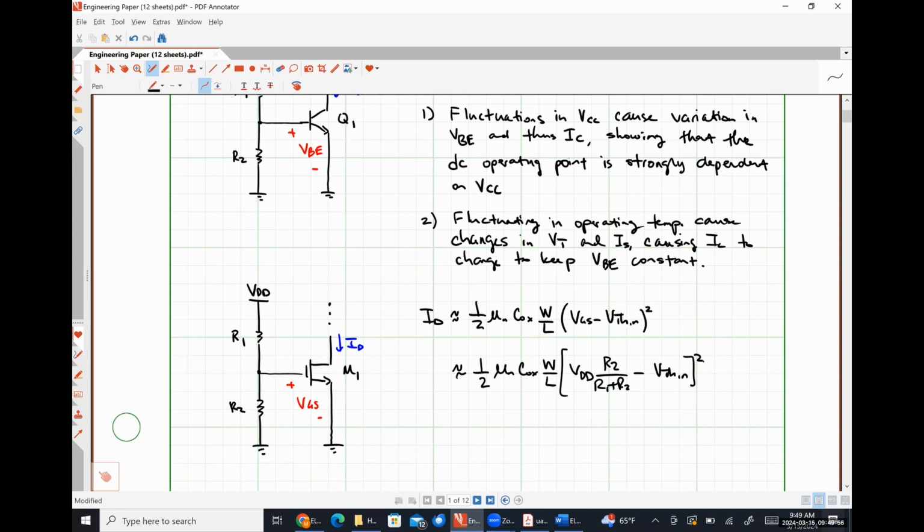So does the voltage that's provided by the battery of your cell phone remain constant? No, it changes with temperature. It changes with how long you use your device, which means all of the different amplifiers and all of that kind of good stuff that are inside of your cell phone, if they changed with just the state of charge of your battery, they would all be absolutely terrible amplifiers because they would all be constantly changing as you use that device. So for sensitive microelectronics, having some dependence on temperature and supply voltage makes it really untenable to be used for practically anything, okay?